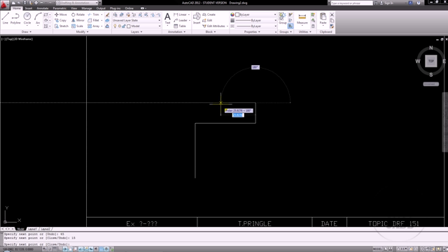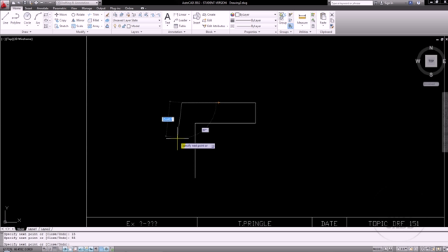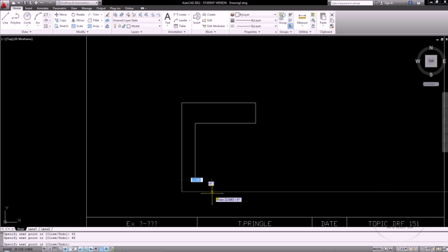back 55. Now this section right here, as it goes down, we need to take into consideration the height of 15 and add it to the 40, so we get 55 plus the 10, which is the thickness of the base, so we get 65. So we've got 40 and 15, which is 55, plus 10, which is 65. So we go 65 here, and then where this would come out 40, we need to add on the 10 from the back. So I'm going to come out 50, and then I'm going to go up 10, and then